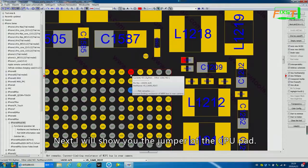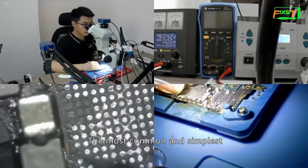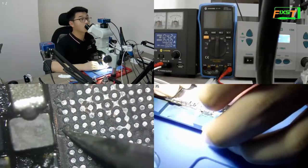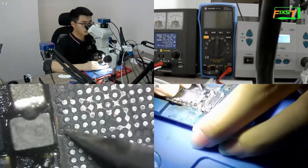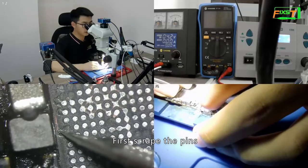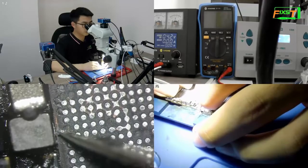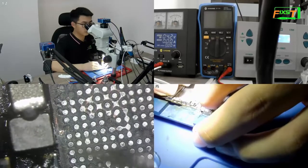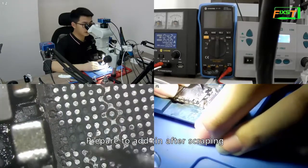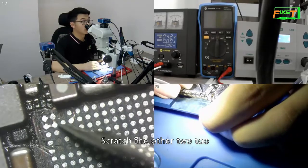Next, I will show you the jumper of the CPU pad, the most common and simplest. First, scrape the pins. Prepare to add tin after scraping. Scrape the other two too.